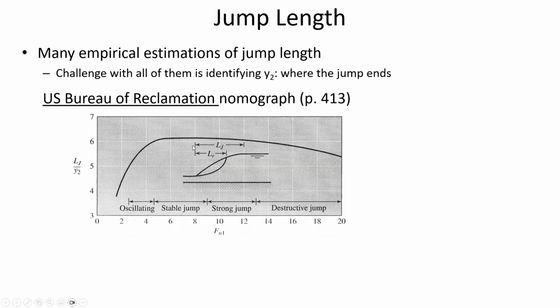And so this is making the point that the length of the rollers, which is where you see a lot of rapid turbulence in the water and sometimes entrained air, those are the rollers. The hydraulic jump itself extends beyond the rollers a little bit further. And so this figure is meant to tell you the length of the jump before it reestablishes